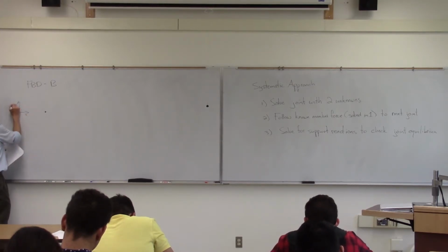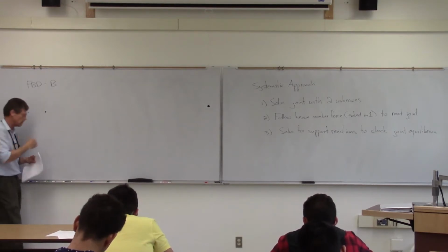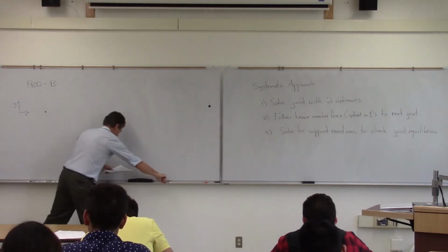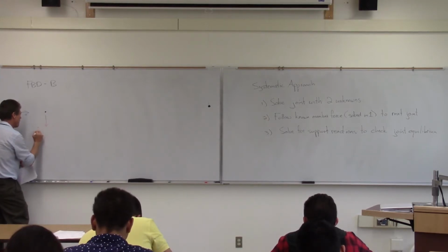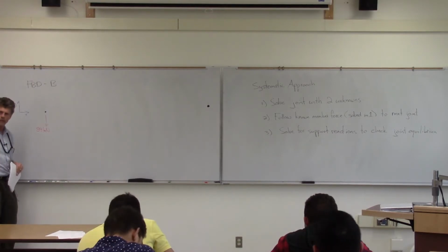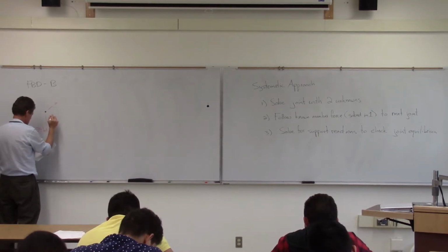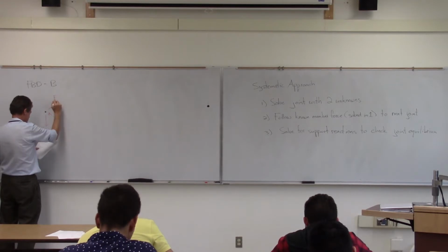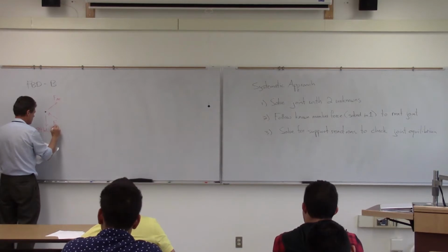And then we're going to choose a coordinate system. Again, it doesn't have to be horizontal and vertical. You can rotate it to the member. Just make sure you get your angles in there correctly. And we put in our known loads, which is vertical, 84 kilonewtons. And then according to the picture that I drew there, will be FAB, FBC.